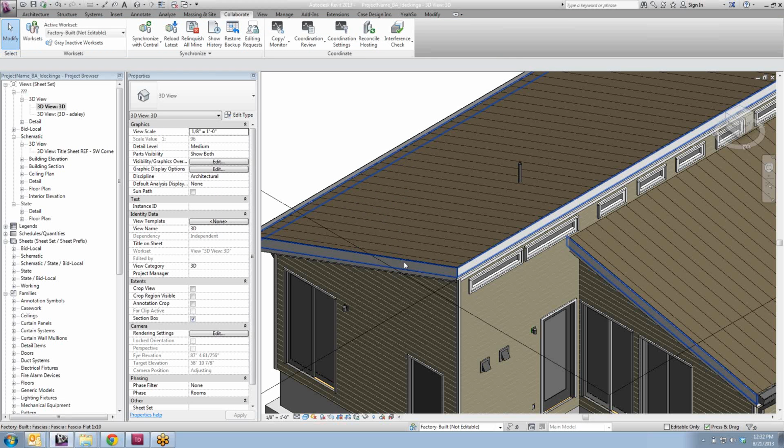I like to keep the modeling as simple as we possibly can, but again, we need to get proper quantities in there for the things that are being scheduled. So if somebody in procurement is taking it, well, do we report the square footage of standing seam metal, for example? And would that extra 2 inches make a difference? We probably do report it. I think the extra 2 inches is within their waste factor, and so that's sort of an offline conversation that we would need to have with procurement about our modeling practices that sadly we haven't had.